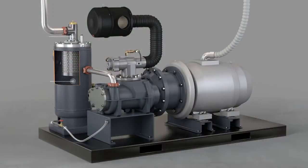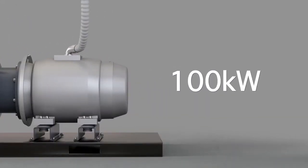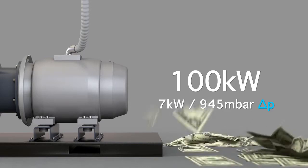As a basic rule, for every 138 millibars pressure difference between the pressure vessel and the delivery port, your motor becomes 1% less efficient, adding 1% more to your running costs. So a 100 kilowatt motor would consume an additional 1 kilowatt for every 138 millibars pressure difference. The greater the pressure drop, the greater the cost.